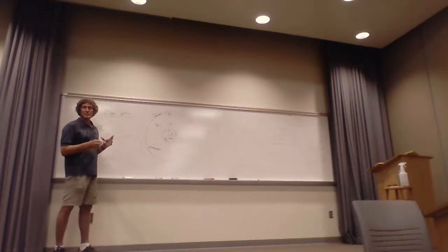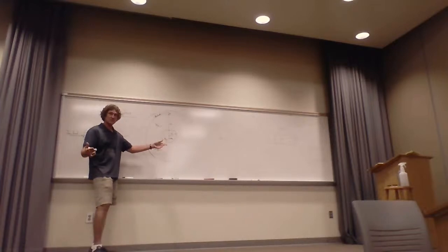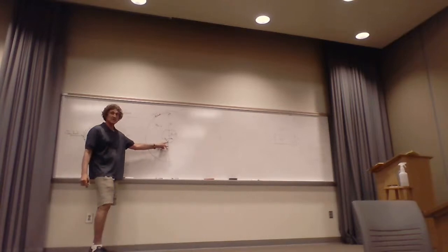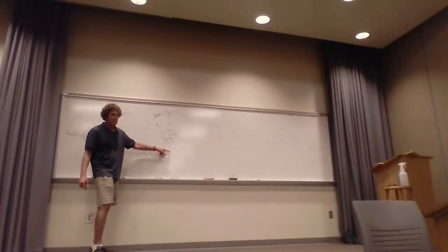They're always going to be circular. Now here's something that does happen. I'm just going to mention this to you. This is called a step index fiber. The inner core has an index of refraction that's constant. This is made of the same material through here. Then it abruptly goes from that index of refraction to the next one. Think about like quartz going to maybe, this won't be it, but like some sort of a polycarbonate thing, something like that.